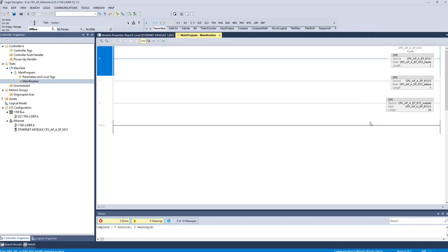So for example, in a valve manifold where you've got coils, using booleans or bits is going to be the preferred way of controlling that. You wouldn't want to try and use, let's say, an integer value to turn on a valve or not. So using a boolean choice for that would be the easiest to use.